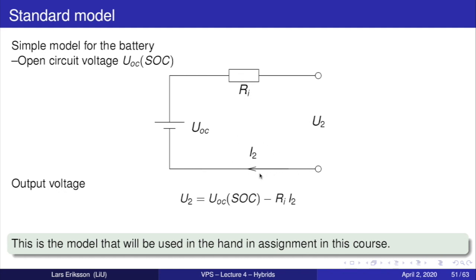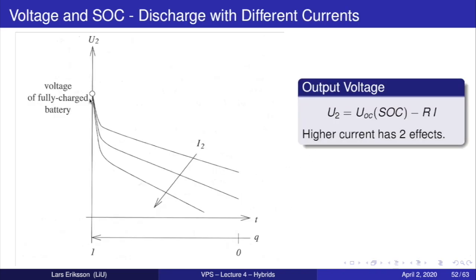currents over time. So we will start with the fully charged batteries and then we'll see how this voltage reacts. So in the beginning we start here, it's fully charged, and then when we start to apply a low current, first it drops quickly, then we get out to a point here where it drops more slowly. If we increase the current, we get a higher initial drop and then it ramps down more rapidly. And finally, with even higher, we go down more.